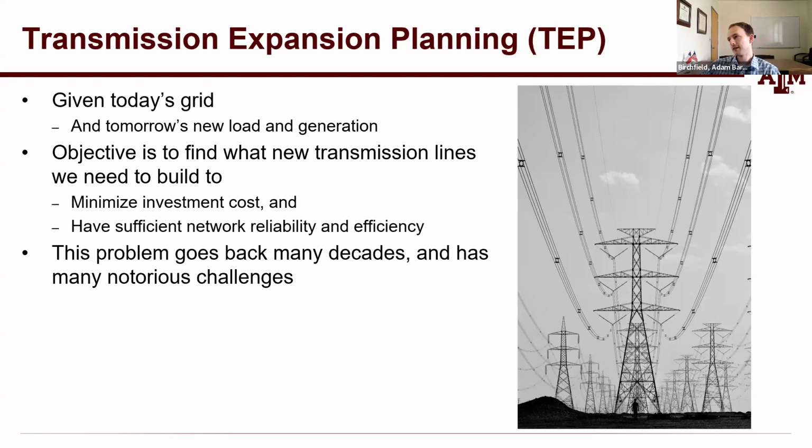So if you do something like average length of a line, that's not going to be the same in Texas as it is in New England or Hawaii, obviously, because the lines are bigger in Texas. And so the geographic length affects a lot of things, right? The line impedance distributions, the electrical distance across a network, things like that.